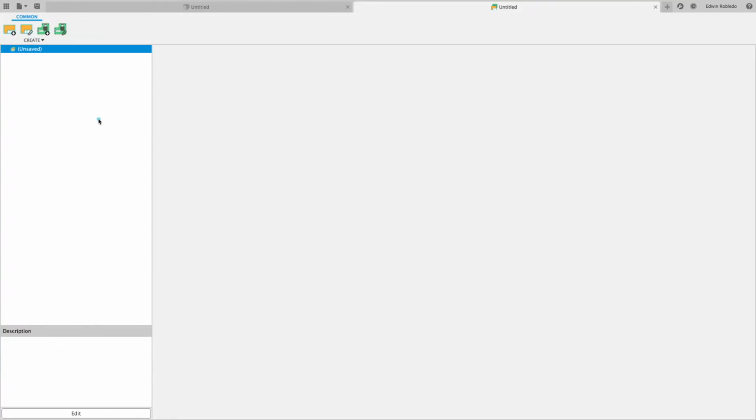The same happens with the circuit board. Actually, I could link an existing circuit board to an existing schematic. Okay, that's one way. Or I could just start a brand new circuit board. In our example for today, we're going to actually start everything brand new. So let's go ahead and click on the schematic here, brand new schematic. And that brings us to the Schematic Editor.